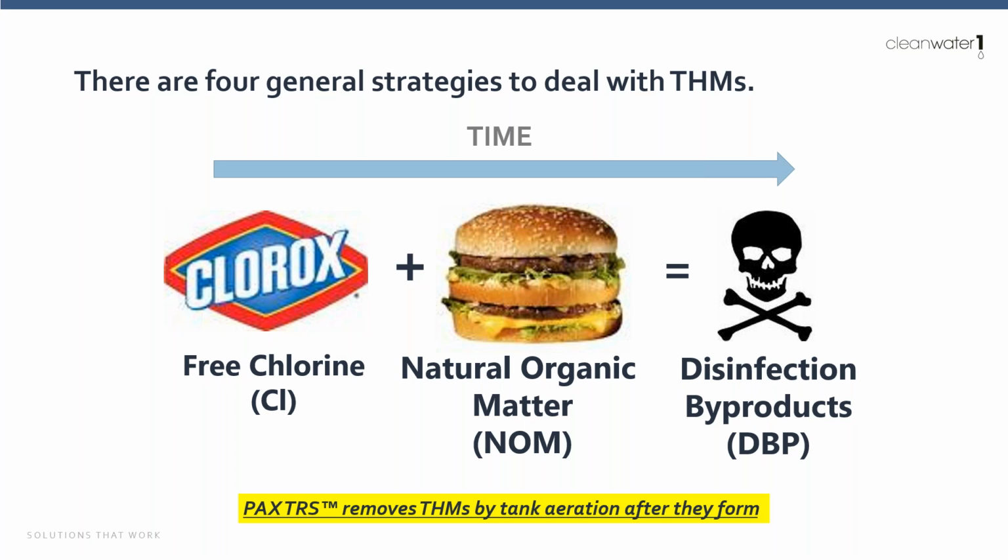That's something that I hope everybody on this webinar today really takes to heart. Protect public health, do the right thing, do your homework, get that NOM out of the water. Start with enhanced coagulation, do the jar tests, call your coagulation and flocculation chemical distributor, make them come in, make them help you. This is really important work, and it's critical that you do that.